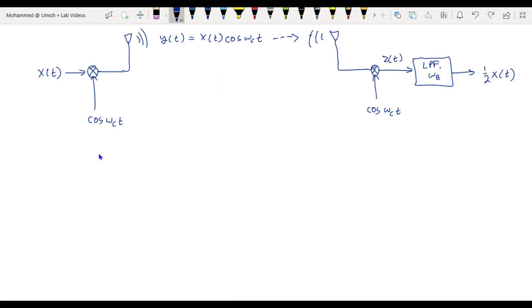Now let's look at how we can construct a demodulator that recovers the original audio signal from our modulated carrier signal y(t). After transmitting the modulated carrier signal y(t) to the intended destination, this double sideband modulated signal has to be demodulated to recover the original signal x(t). We can't use an envelope detector, since the envelope detector would return the absolute value of x(t), not x(t), but it turns out that we can demodulate y(t) using the following two steps.